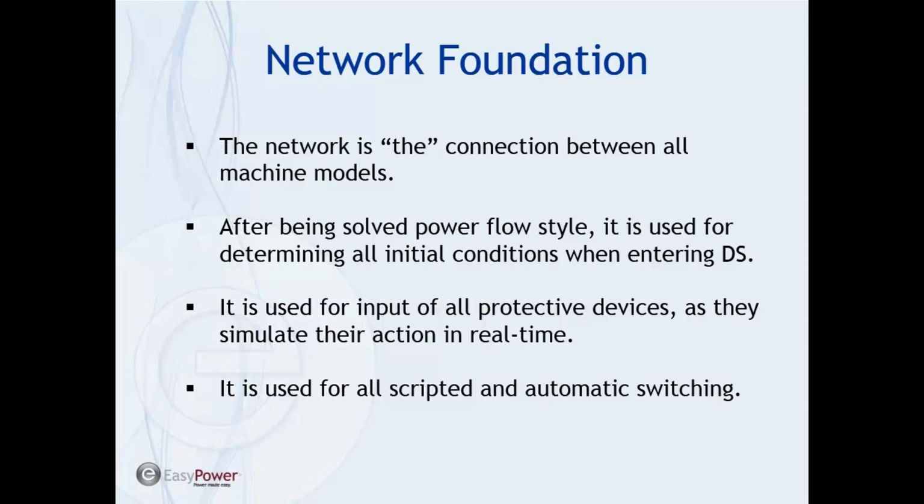It's used for the input of all protective devices because they need branch currents, they need transformer current flow, they need these values to have an input so they can perform their real-time action. And it's used for all scripted, script being some statements that we can write to perform a simulation in a particular order, for all scripted and automatic, that is, if a breaker trips automatically, switching actions.